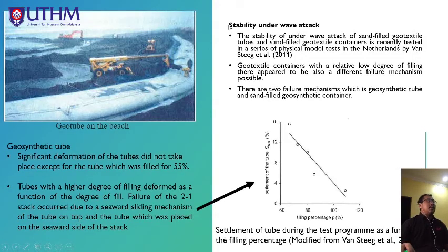The second subtopic is stability under wave attack. The stability under wave attack of sand-filled geotextile tubes and sand-filled geotextile containers was recently tested in the Netherlands by Van Steeg et al., 2011. For a geotextile container with a relatively low degree of filling, there appears to be a different failure mechanism possible. There are two failure mechanisms, for the geosynthetic tube and for the sand-filled geosynthetic container.